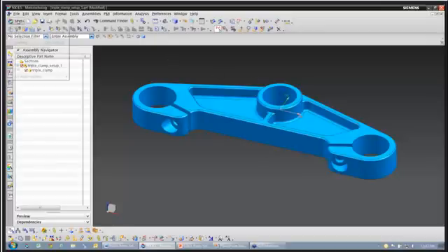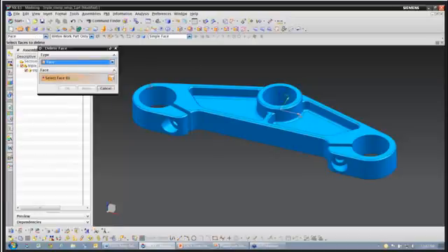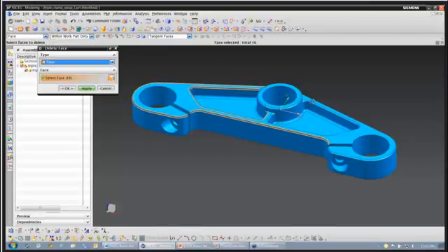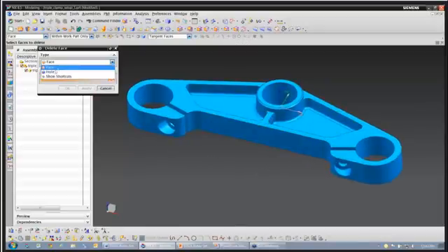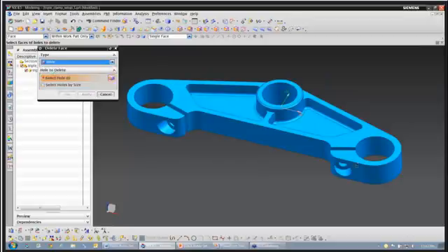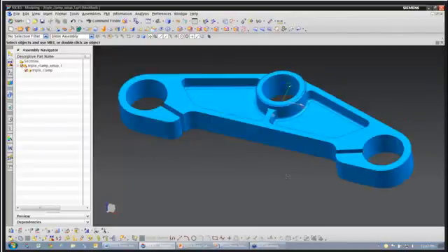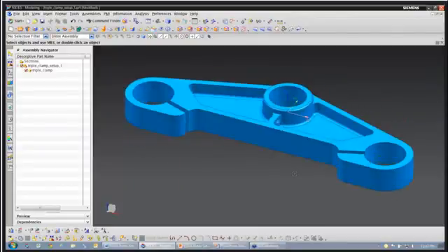So I'm just going to go over to the modeling environment here, and I'll delete these chamfers around the outside of the part and around these pockets here. And for example, if these holes are going to be machined in a different setup and we don't want these holes in this part, I could delete those holes out of there. Alright, so this would now be our manufacturing model.